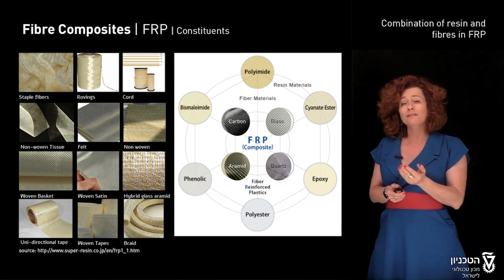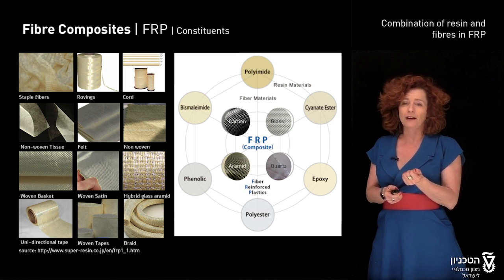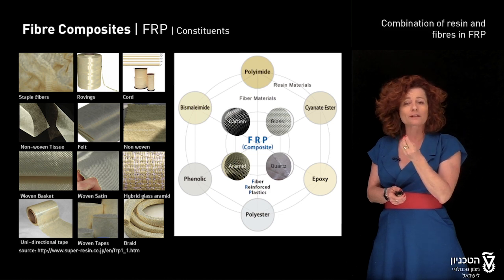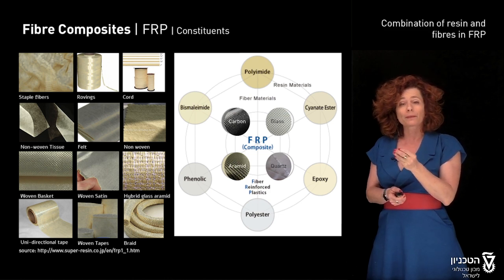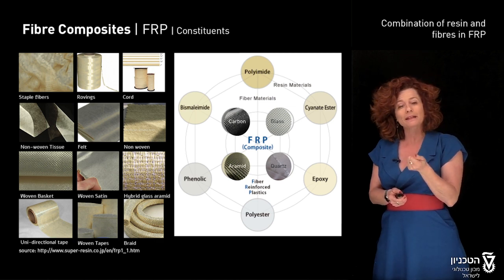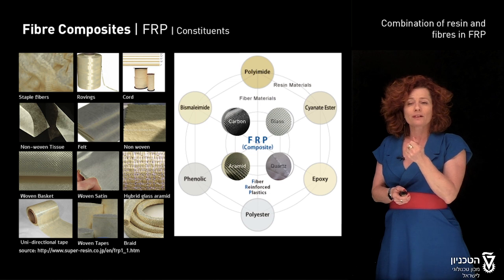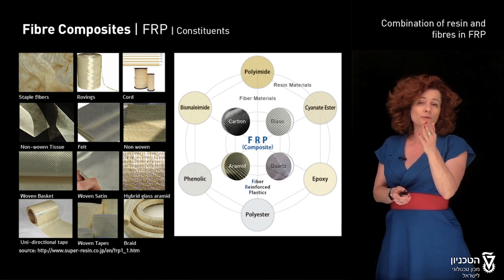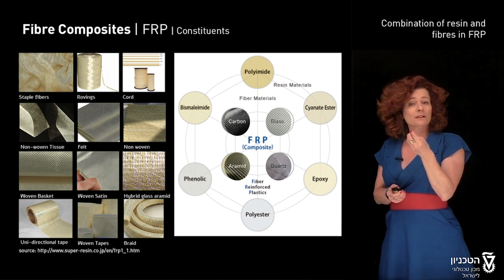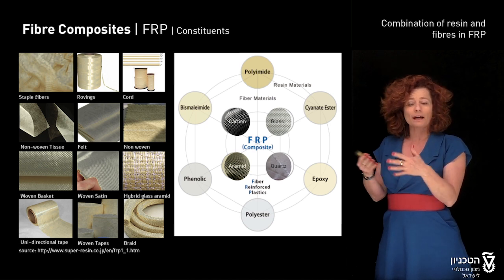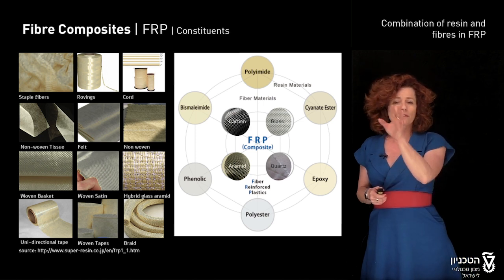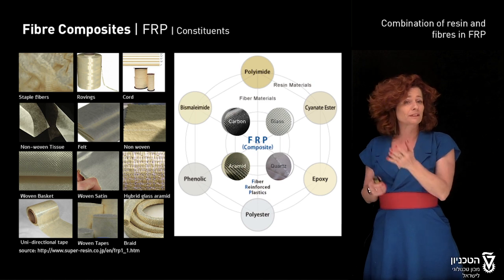So on the left, you see different forms of usage of fiber material. All the fibers here are aramid, Kevlar. You recognize those by the yellow color. Nevertheless, you see different forms. You start from staple, which is a very basic raw form on the upper left, short fibers, all the way to roving, which is some kind of a thread or cord. And then afterwards, textile construction, as you would see woven material, knit material, and even braided material. So these varieties and more could be applied to different types of fibers.